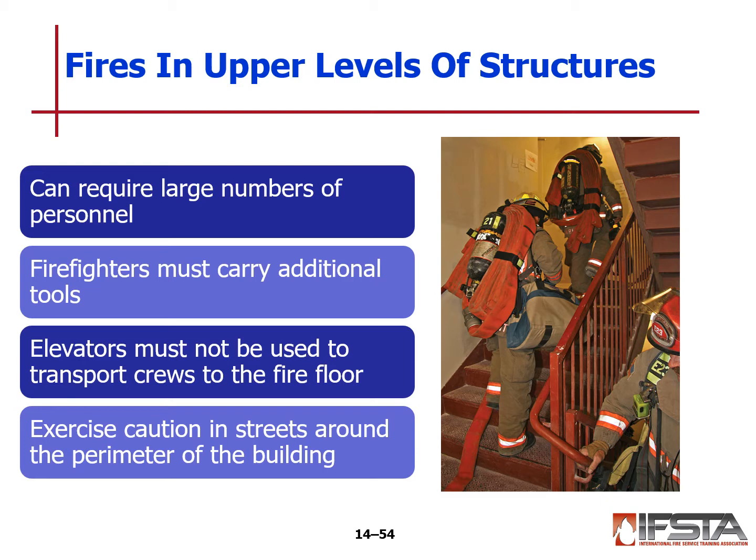Elevators cannot be used to transport crews to the fire floor itself. You can utilize elevators in multi-story buildings, but you need to be cautious in doing so. You can transport equipment and firefighters, putting them in fire service mode, but you're not going to take that to the fire floor. You're going to go a couple floors below the fire floor as an example, if that elevator is usable, and then you're going to advance from that point.